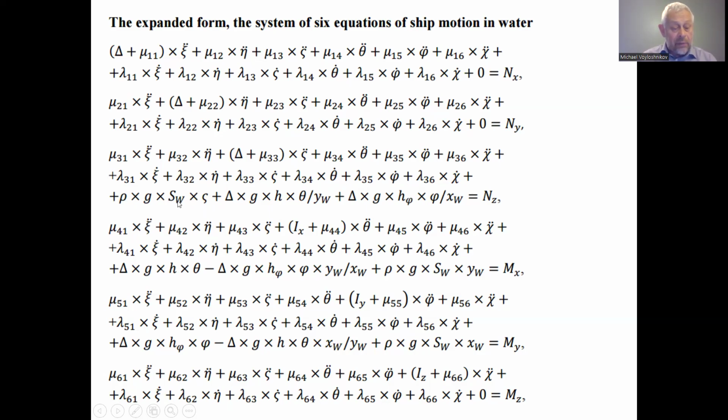And when we find the product of the submerging or emerging volume when the ship experiences the vertical rocking, we multiply this volume by the water mass density and by the gravity acceleration, and we can find the force.